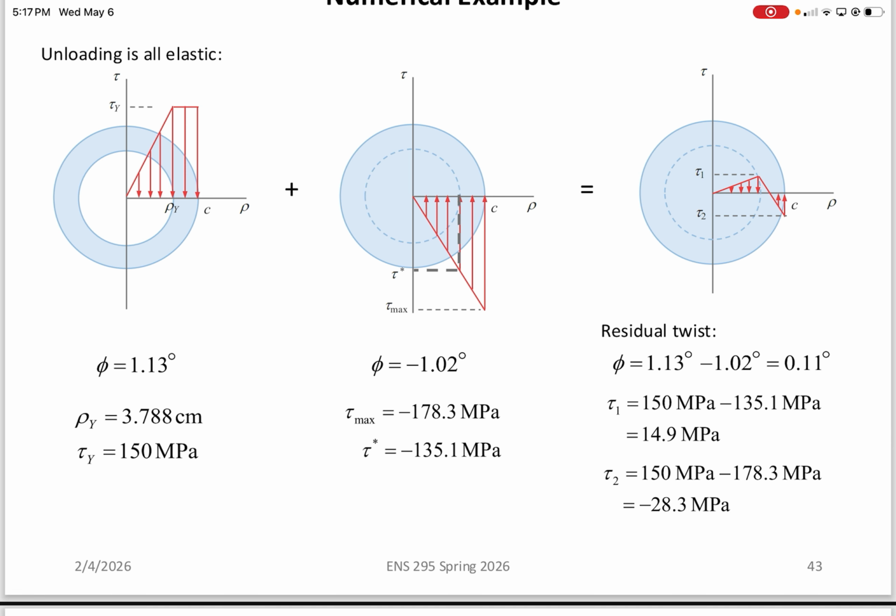It's not an actual stress, but it does behave according to linear elasticity, so it's going to be a difference. That's how plasticity is characterized, through the definition of residual stresses: whatever the stress is according to linear elasticity that exceeds the yield stress, minus the yield stress. So it's how much more the stress is over the yield stress.